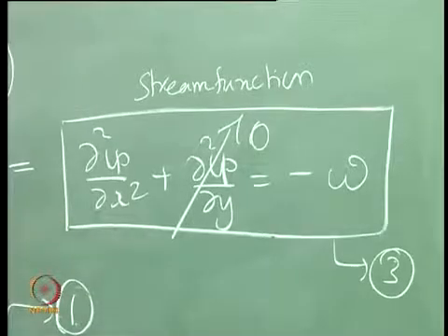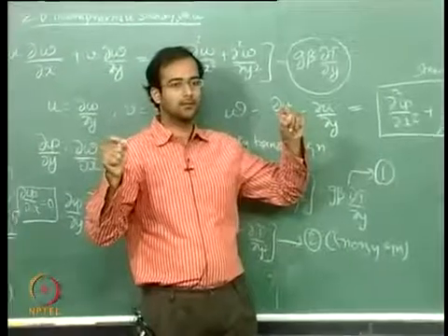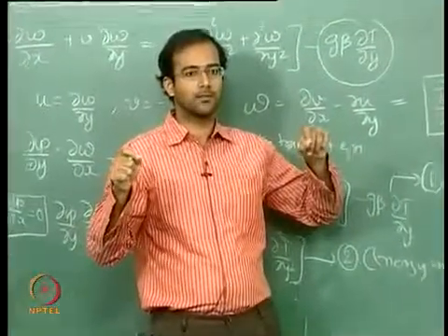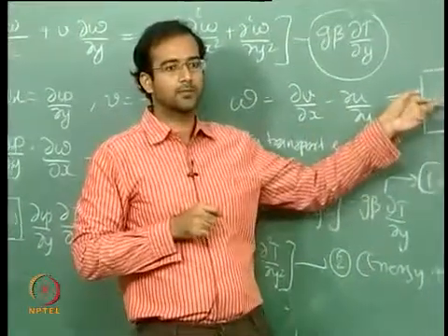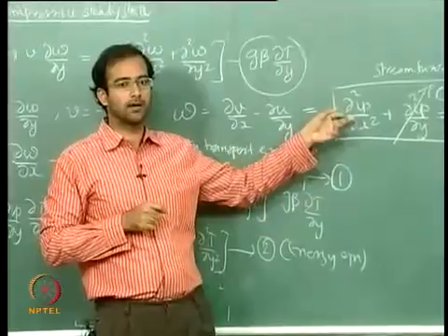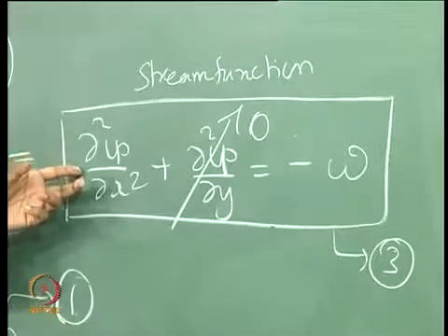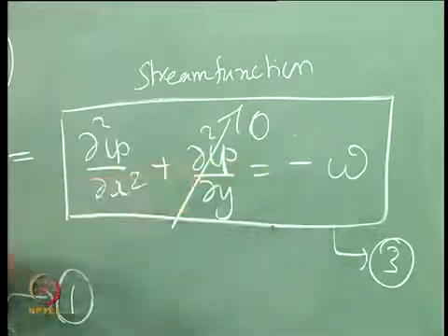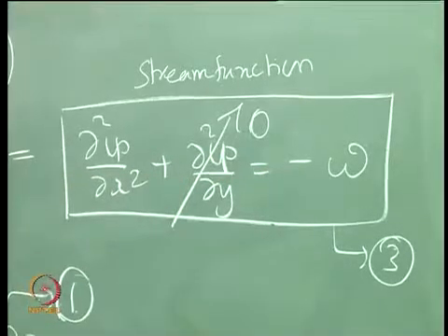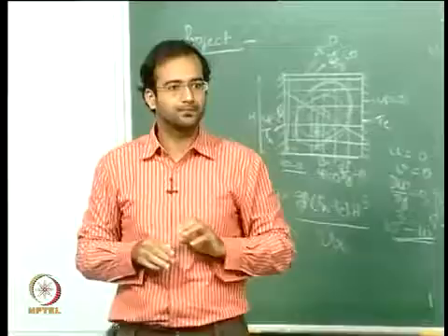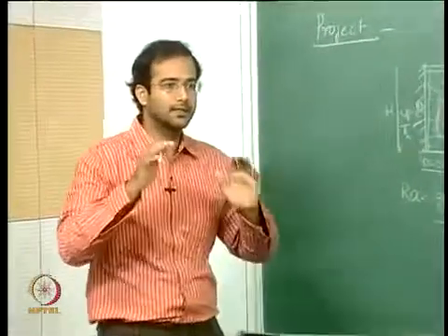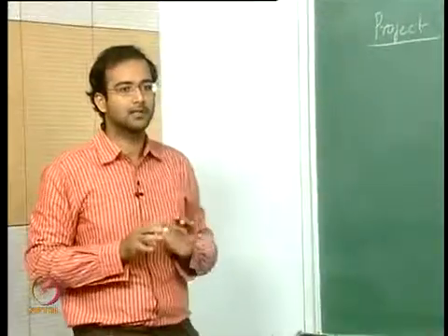You can write as simple Taylor series expression for the boundary in terms of the interior point, and you can express this in terms of the stream function at the boundary. So therefore you can directly calculate your vorticity at the boundaries. All this is very clearly explained in the document. So please read through the document. If you have any questions, you can ask me.